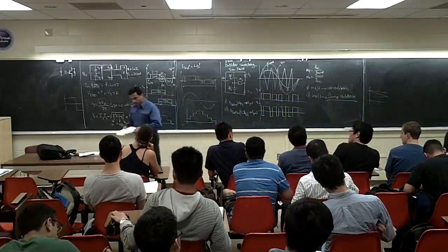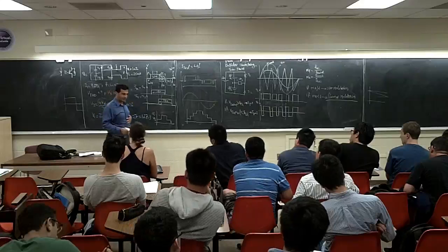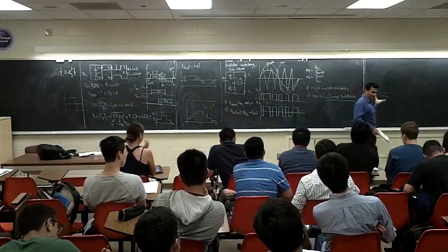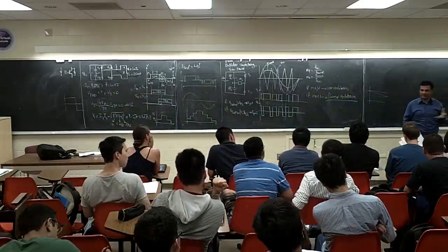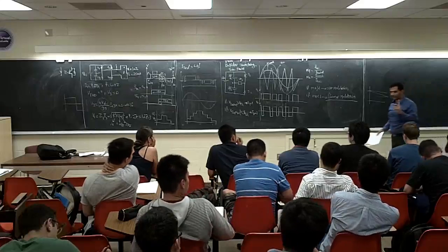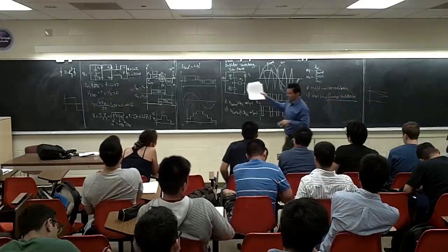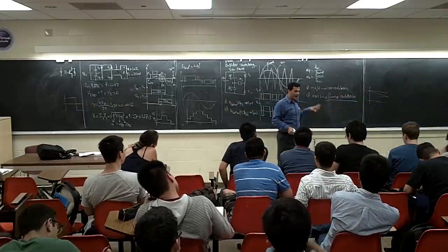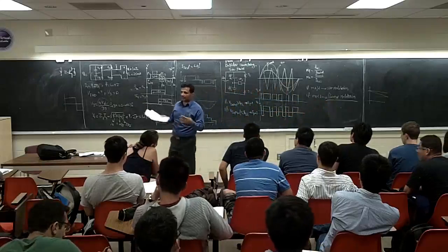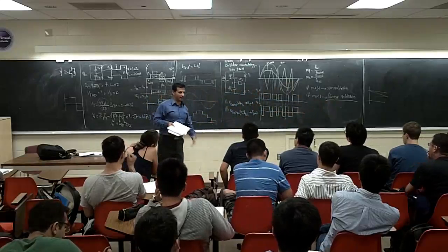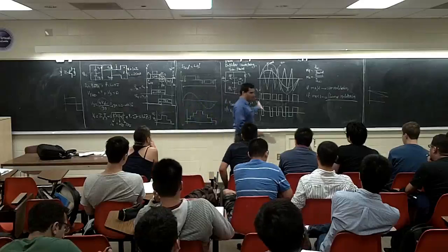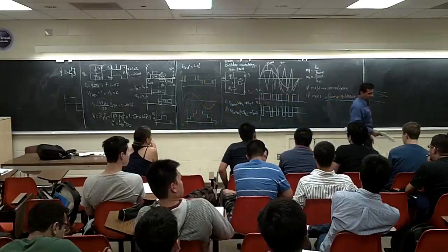Now, what is important for us under the linear modulation? I have this MA, MF, and I have V_DC. What is important for me is V1, right? I need to find a relation between V_DC, MA, and V1. V1 is the fundamental harmonic, right? Because that way I can select this one. If I select 0.8 MA with this much V_DC, I'm going to get 110 volts out. We need to derive those equations to see how this thing is going to work.